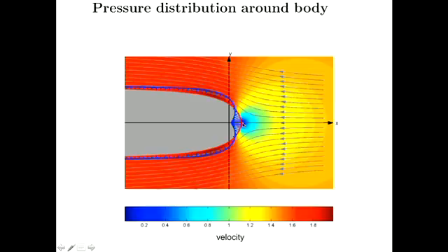Actually, we've got zero velocity right on the nose because we know there's a stagnation point there, all right? Low velocity means we're going to have elevated pressure, a pressure higher than P infinity. And in fact, when that flow stagnates, we know we're going to have a pressure coefficient exactly equal to 1.